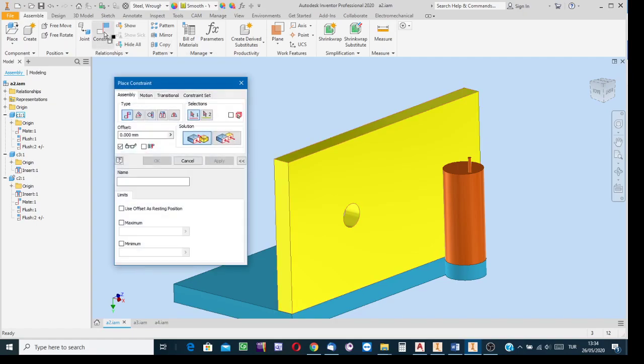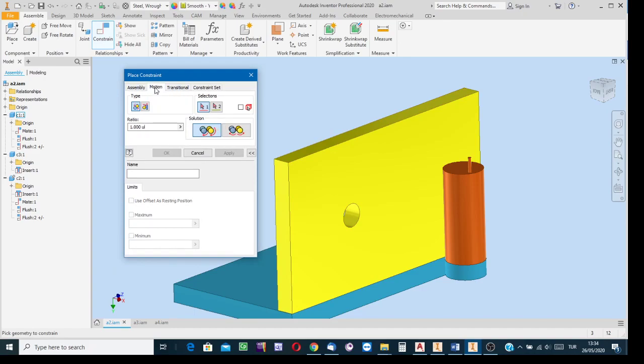Input the motion type constraint. Click on the constraining button, bring up the dialog box, and select motion type. One surface is flat, so select this type, and this solution is the correct one. At present the distance is 1. Then the first selection tab is on. Indicate which one first. Bring the cursor to the vicinity of the edge of this revolved body. See that the highlighting is on the axis. The longitudinal axis is highlighted in red and there is a banded arrow. Say that it is the first feature, and indicate with a click.